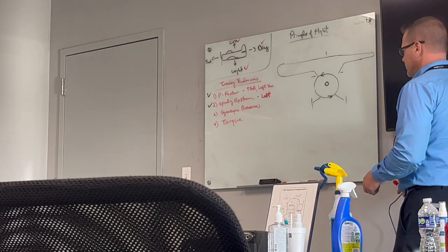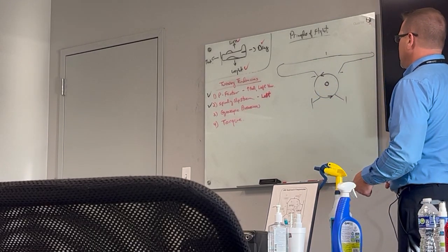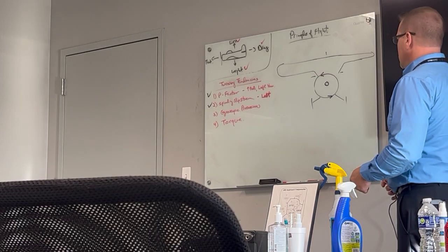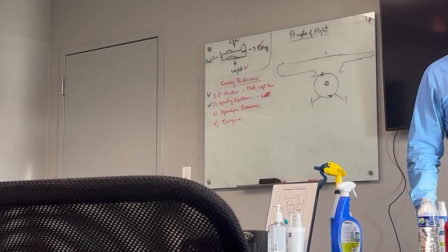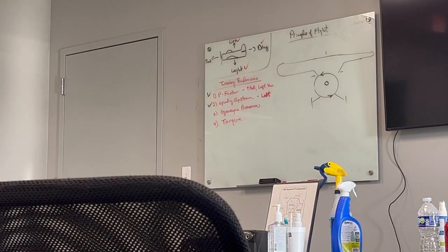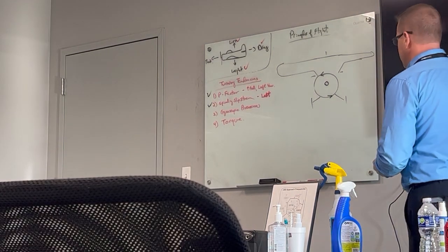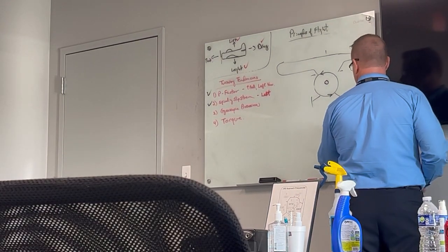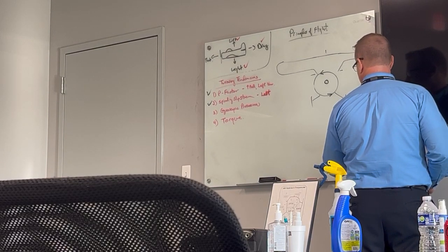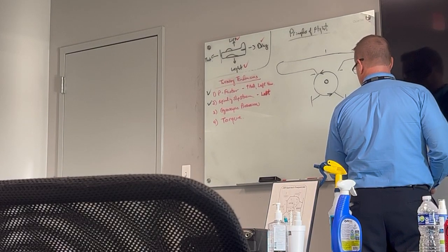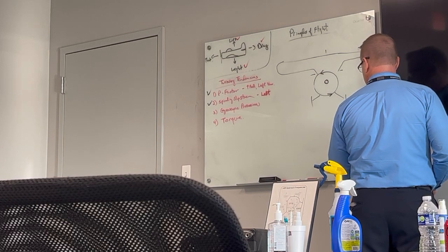So, when do we typically apply gyroscopic force to this? Well, we do it when we pitch our aircraft up or down, okay? That's going to move that disc. That's going to basically take that disc that's spinning out in front of us there, and we're either going to be pitching it in an upward direction, or pitching it in a downward direction.